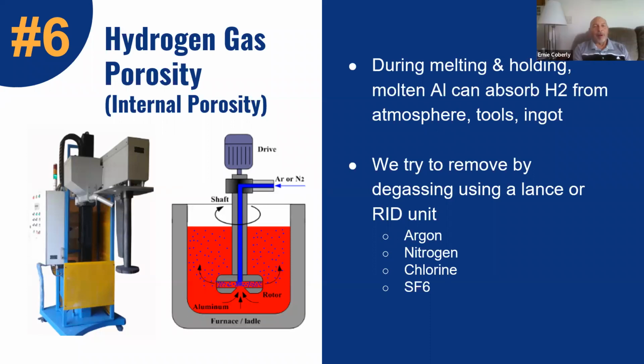This goes to what Brad is talking about, that there's always gas in a casting. It's not necessarily to your advantage to have it gas free all the time. It's a match up to what your customer requirements are, to what the casting is, and it's an economic matchup. It depends on where you want to go with your part. Adding gas in takes up some of that shrinkage porosity we talked about. It takes up some of that volume expansion and spreads it out, so you tend not to congregate your shrinkage. Very common practice. And Brad will talk a little bit later about why it's so important to identify the gas level you have and then know the gas level you want, because it may be two different things. You just can't always get it all out.